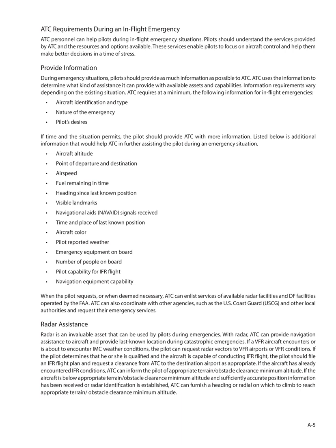If the aircraft has already encountered IFR conditions, ATC can inform the pilot of appropriate terrain/obstacle clearance minimum altitude. If the aircraft is below appropriate terrain/obstacle clearance minimum altitude and sufficiently accurate position information has been received or radar identification is established, ATC can furnish a heading or radial on which to climb to reach appropriate terrain/obstacle clearance minimum altitude.